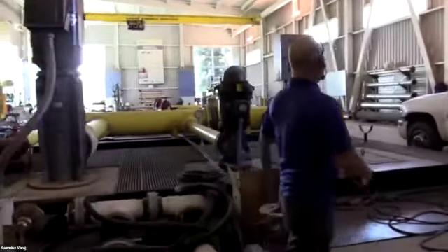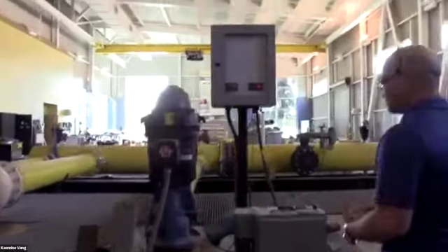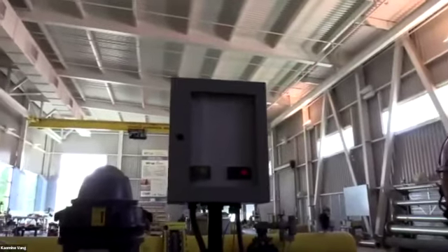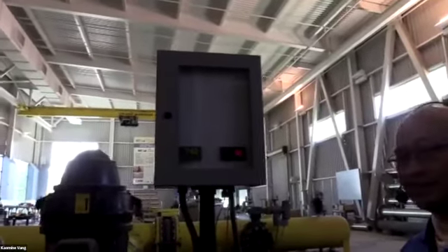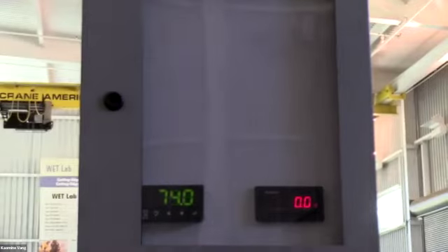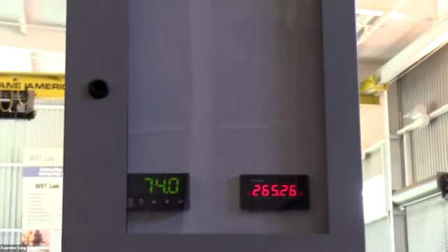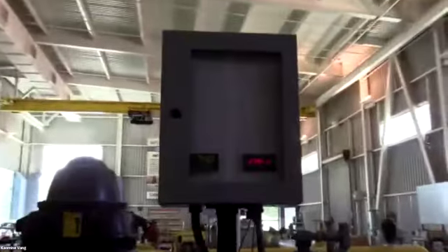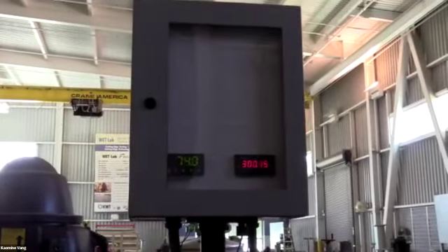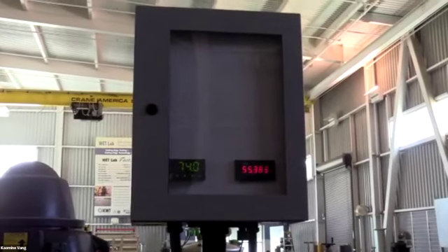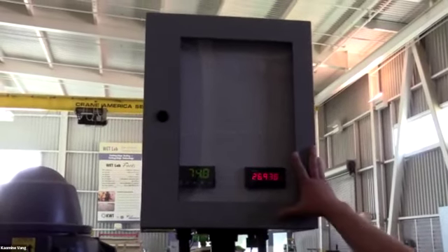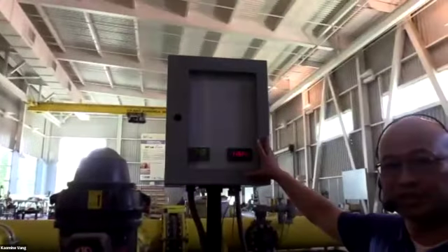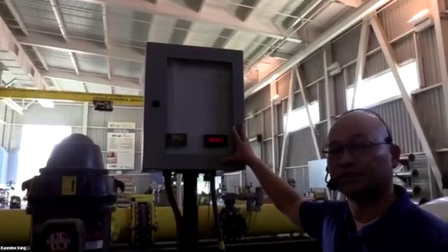But the way VFDs work is based on hertz, or frequency, which then translates into rotations. So here you have temperature, that's the temperature of the water in the sump. And as the pump goes faster, the rotations go faster and you get a higher reading on your rotation. That's the idea behind VFDs. The higher the frequency, the faster the rotation goes, and that's how you get your RPMs to change. So that's why we have this, so that we can measure the rotation and the speed based on what the frequency is for our VFDs.